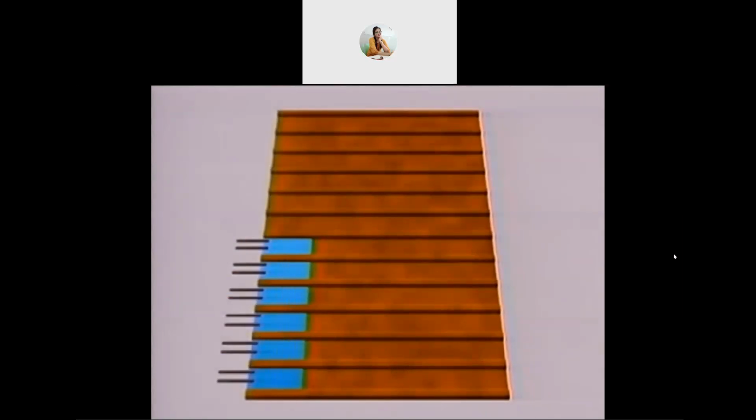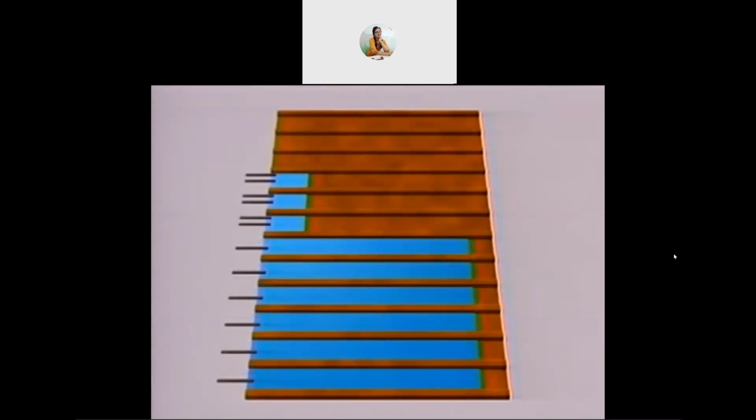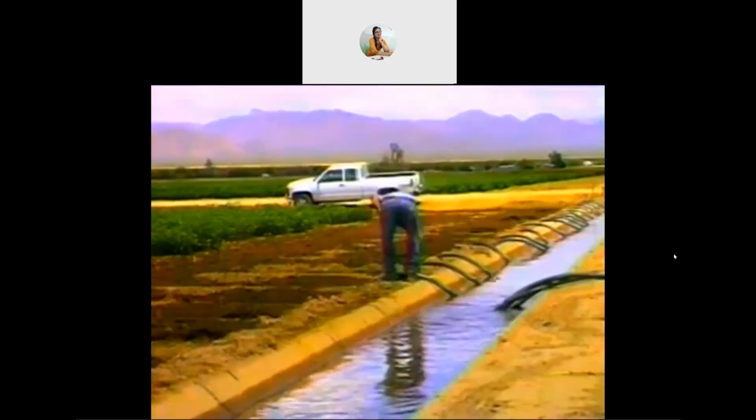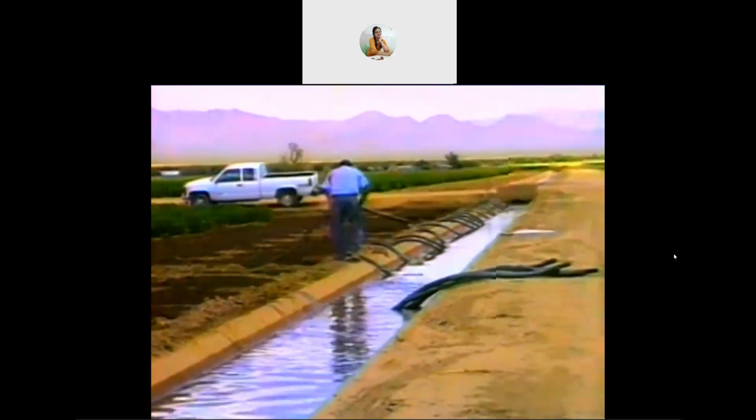We could minimize deep percolation by increasing the flow rate and shortening the set time. Notice that now we have less deep percolation. Unfortunately, we lose more water in the form of runoff. If we tried to minimize runoff by using a smaller flow and increasing the set time, our uniformity would be worse. We lose more water due to deep percolation at the head end of the field.